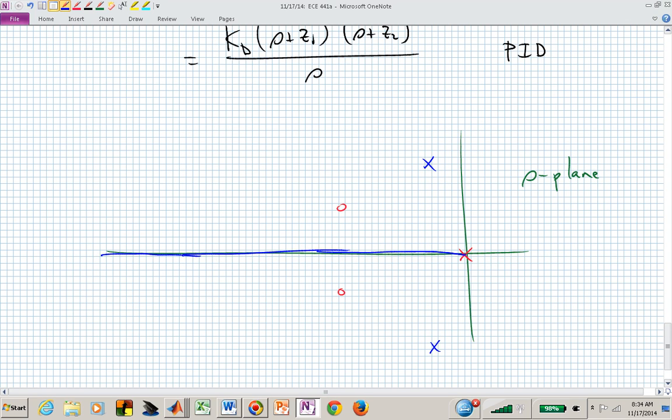That's now reduced my pole zero excess behavior of the system. This guy is probably going to just march off there, and these two are going to approach those finite zeros. That's now the root locus pattern for two zeros that are complex conjugates.